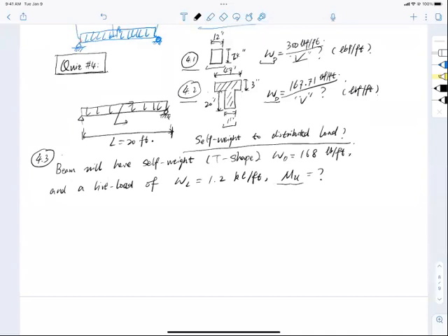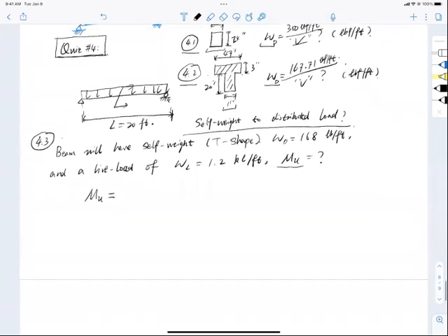All right, all we need to do is Mu equals, what is the moment equation for Mu? Austin, Mr. Eisterhold, are you there? Hey, how are you doing, man? Good, good. So what is the moment for a simply supported beam? 1.2 dead plus 1.6 live. Sure, 1.2 dead MD plus 1.6 live ML. That's correct. Now how about the moment equation in terms of MD? That is what?